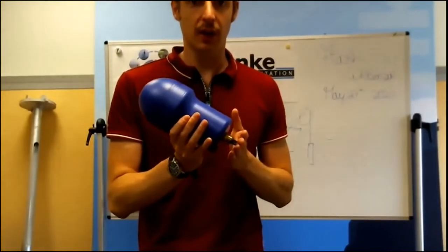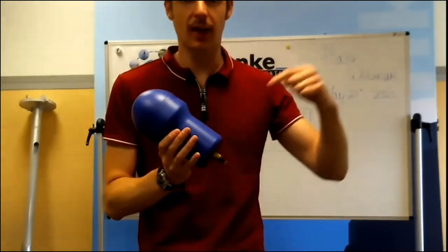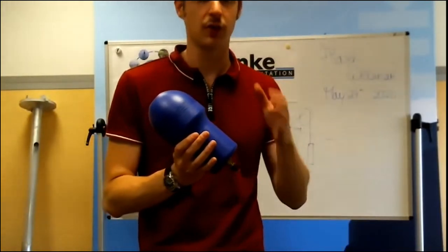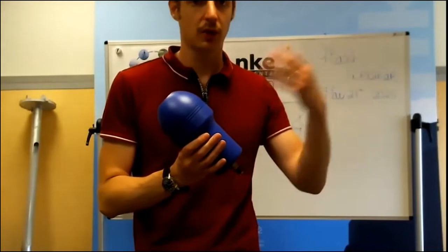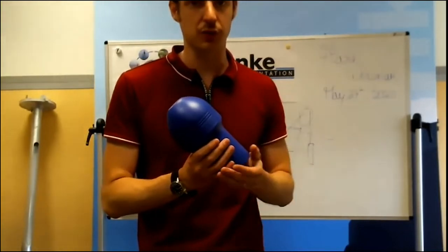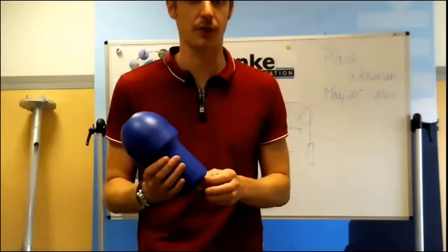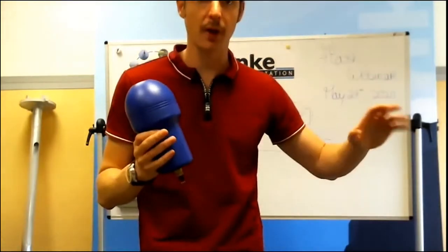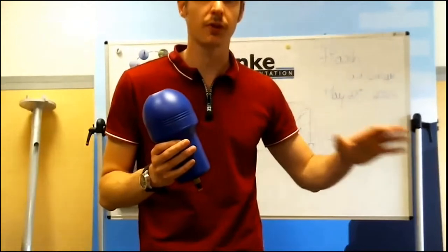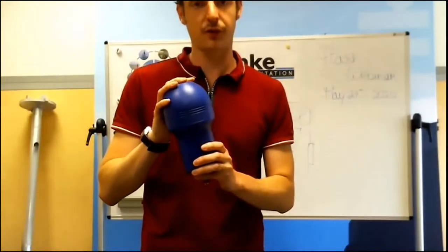This is directly programmable inside the sonde interface. So you can directly program how long and how often you want to transmit the data, together with how often you want to measure the data. So you can totally separate the frequency of the measurement of the WiMo and the frequency of transmission of this module.